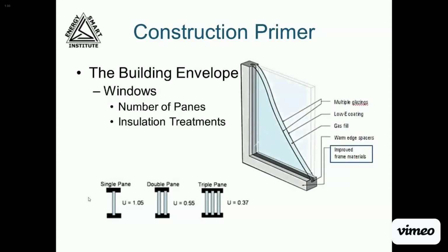Window frames made of fiberglass or wood help increase the thermal resistance of windows. Metal window frames can conduct heat very quickly, as metal is a great conductor. Thermal breaks of some type of rubber or insulation or other non-conductive material between the inside and outside window frames are commonly used to prevent this conductive energy loss.